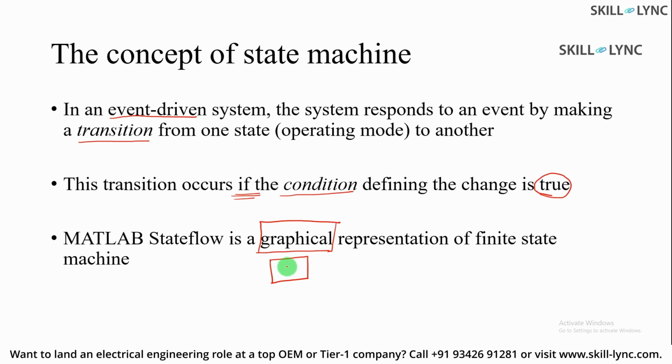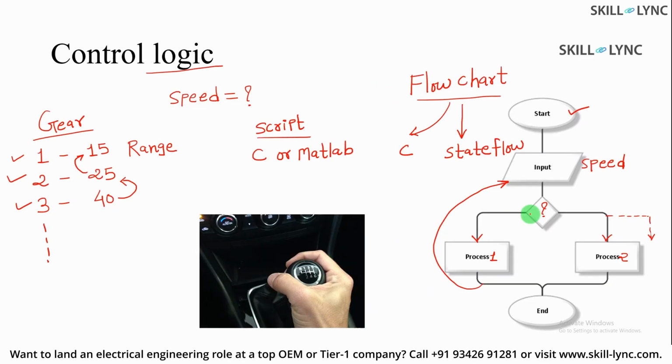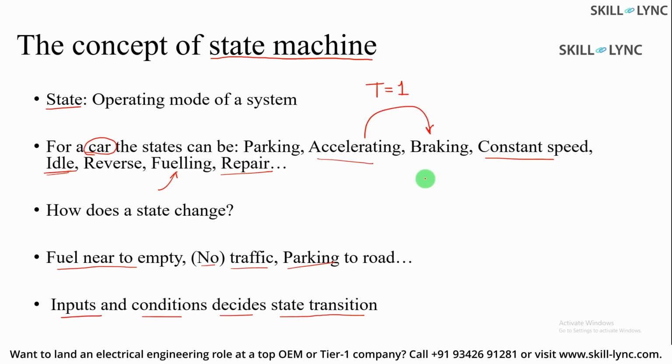Here you have a block 1, here you have a block 2, and you can decide when the state is going to change from block 1 to 2, or from block 2 to 3, or maybe again back to block 1. So the MATLAB Stateflow is a graphical representation of your logic. Whatever is your flowchart or your logic, that can be implemented in a MATLAB Stateflow environment.